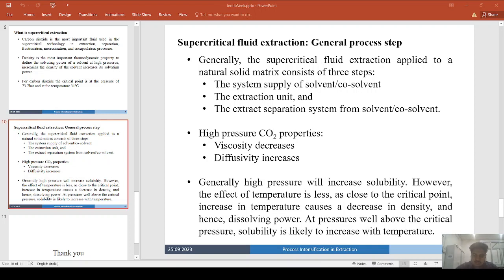So now let us discuss what are the applications for the supercritical extraction. One of the examples is essential oil extraction. Isolation of essential oils such as the other oils. The use of carbon dioxide as a supercritical fluid has been considered a chemically green, unconventional extraction technique that does not alter or degrade the substances present in oils because it uses relatively low temperatures in the extraction process.